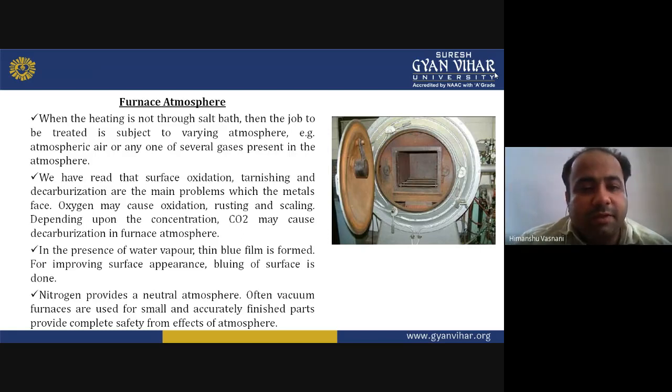In the presence of water vapor, a blue thin film is formed. So for improving surface appearance, bluing of the surface is done. Now nitrogen provides a neutral atmosphere. Often vacuum furnaces are used for small and accurately finished parts, providing complete safety from the effects of atmosphere.